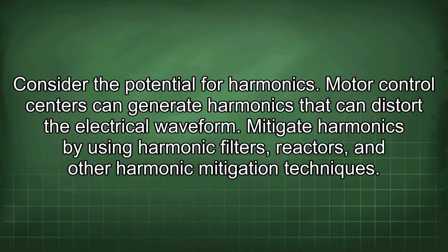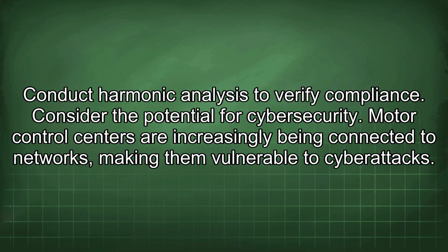Consider the potential for harmonics. Motor control centers can generate harmonics that can distort the electrical waveform. Mitigate harmonics by using harmonic filters, reactors, and other harmonic mitigation techniques. Conduct harmonic analysis to verify compliance.